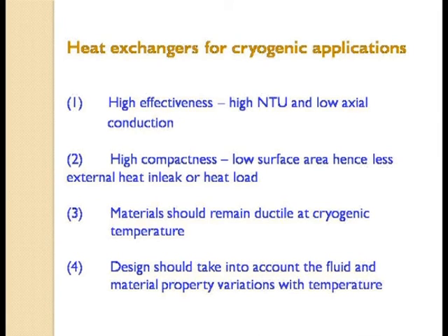Okay. And in fact, in earlier days when aluminum brazed plate pin heat exchangers were not coming up very satisfactorily, in those days shell and tube and coil tubes were used, and these are also being used, but more often people go for aluminum brazed plate heat exchangers because of their very high compactness, better compactness and better performance compared to the other two heat exchangers.